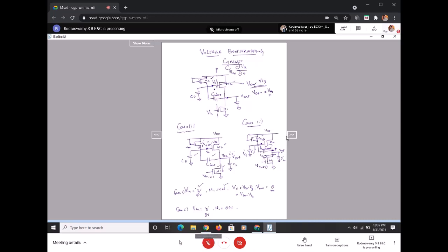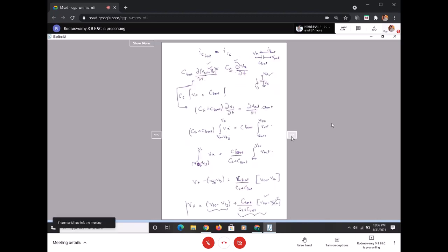Yes. So now I have to add some voltage, increasing Vx from VDD minus VT3 by some extra voltage, ensuring that my Vout, worst case, when the input is low, should become 1, that is VDD. And that is exactly what we are trying to do in this case. Hope this is fine. What is that extra? It is C boot divided by CS plus C boot, into VDD. Is that clear now? So what does your Vx eventually become?